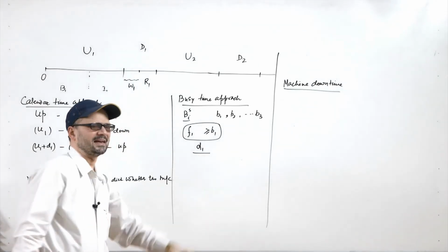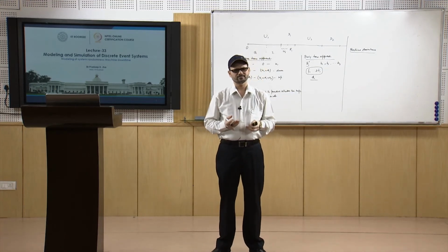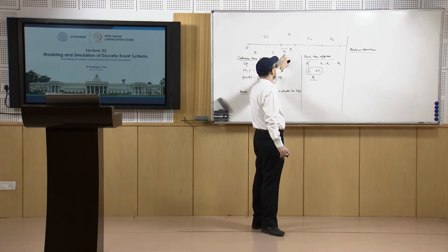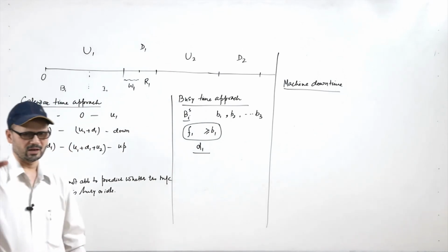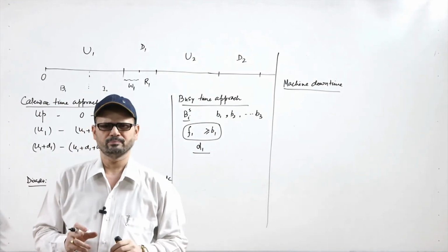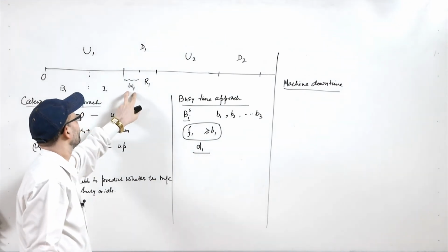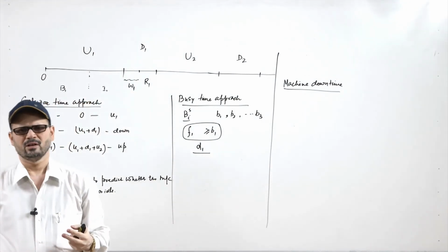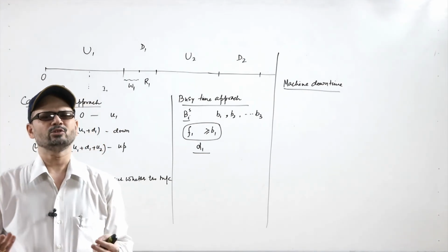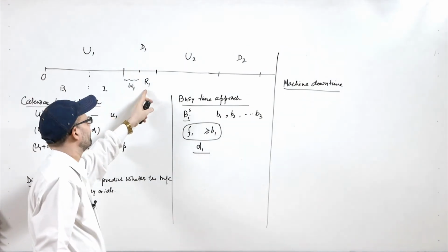Now, the thing is that either this W1 will be significant or it will be insignificant. So, in the case of insignificant values of W1, you have to point more towards the R1s, that is the repair time. Because W1 will vary depending on the cases, whether the repair persons are available. If they are available, in those cases this W1 will be 0, and then you can just have these R1s.